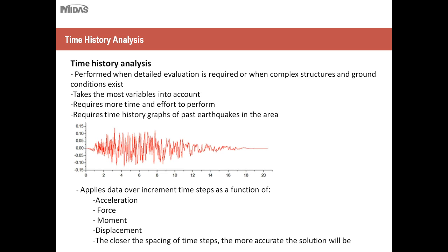Typically, companies that work in seismic regions, or projects located in high seismic regions or in California, use time history analysis very regularly, whereas for companies out on the East Coast or the Midwest, response spectrum analysis is the most prevalent.